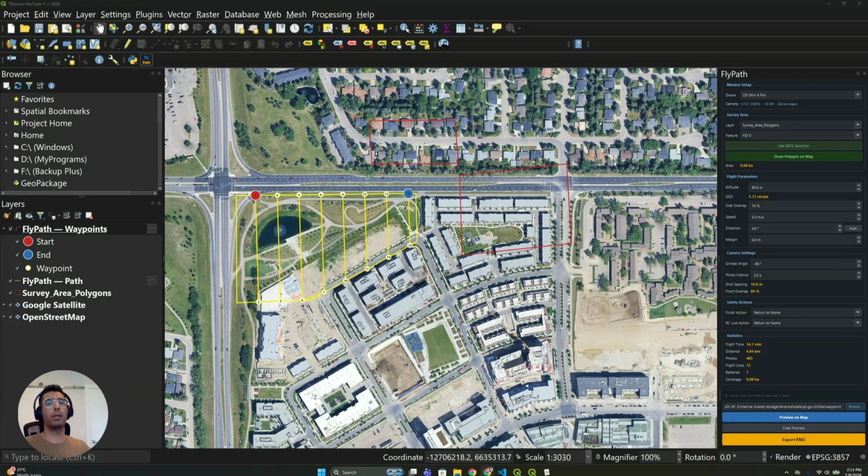The reason that I'm going to use this version is that it has a button that finds your RC controller automatically along with the existing waypoint files, so that you can make sure which waypoint files you're going to replace. You just plug the controller into the computer with the cable, and then FlyPath sees it, also sees the waypoint mission files, and shows you their paths, so you can see what's actually already there.